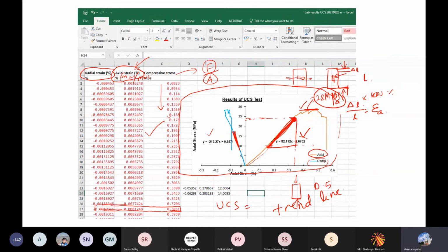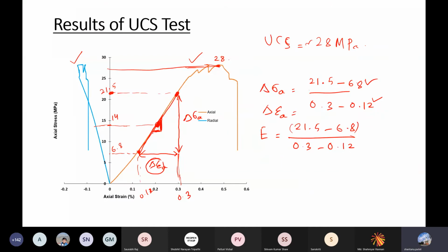What I did here was I took some data points from here to here in this range, and plotted them again on top of this. And there is something called trend line. Add a trend line. Those who don't know about Excel much, you can just Google this, and you'll find a YouTube video to do that. So add a trend line, and there is an option to show what is the slope of this trend line.